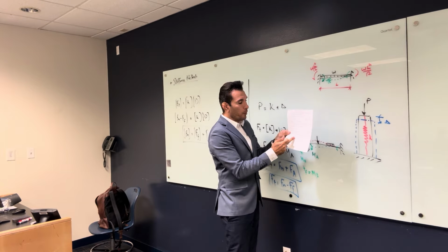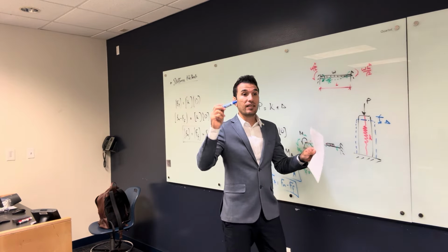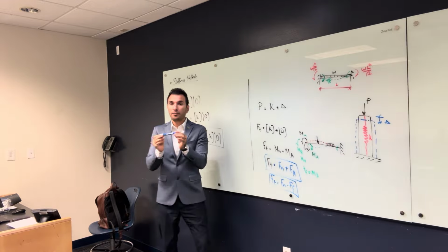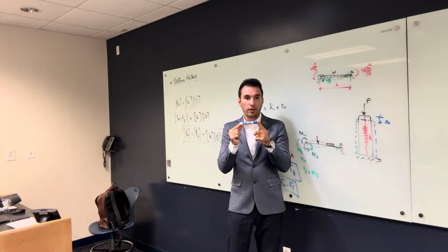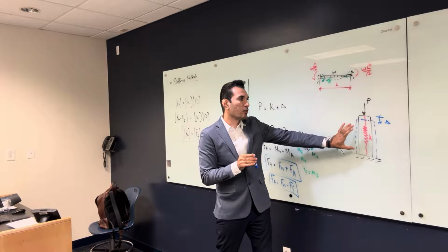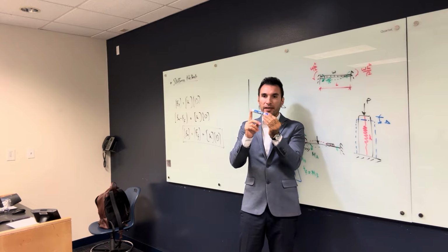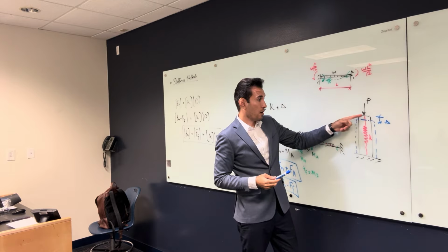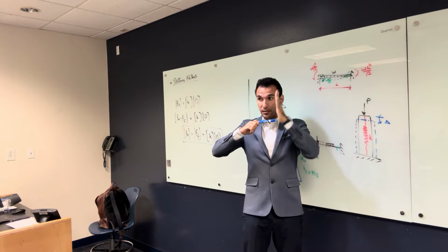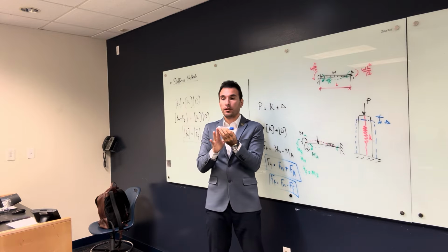So I'm telling you how to build the element stiffness matrix for any structural member. I said number one, determine the degrees of freedom. Like let's say we have a bar that means it only takes axial deformation, like a truss member. For a truss you have two here and two here, right? It can move X and can move Y. For springs, it's usually one here and one here, because the spring only gets compressed, it cannot take any force like this. So number one, determine the degrees of freedom, okay?